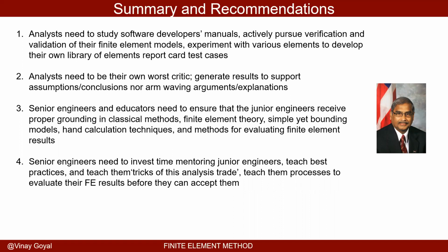Senior engineers need to invest time in mentoring junior engineers. This is very important. And they teach best practices. What are the best practices? Just like what I'm talking about. Teach the tricks of the trade, of this analysis trade. Teach them the processes to evaluate their finite element results before they can accept them. Your null hypothesis always should be, my analysis is wrong. You should go and prove that your null hypothesis is wrong, and therefore your solution is in fact correct.